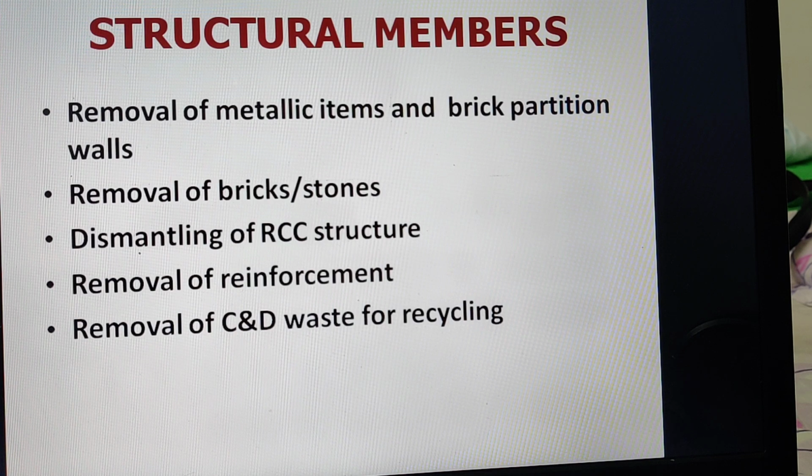If we talk about the structural members, we are to remove the metallic items and brick partition walls if possible, then remove bricks and stones if they are to be reused, and then dismantle the RCC structures.